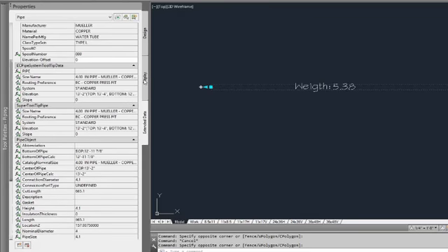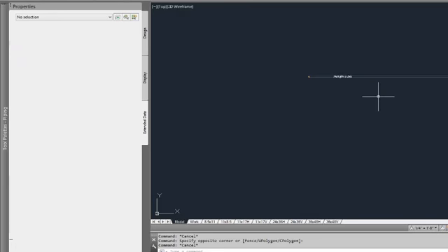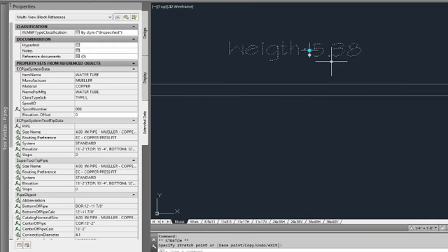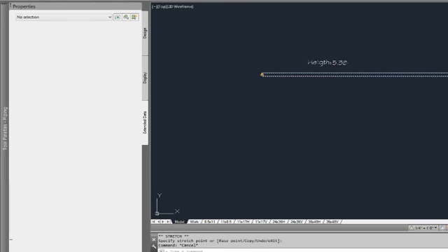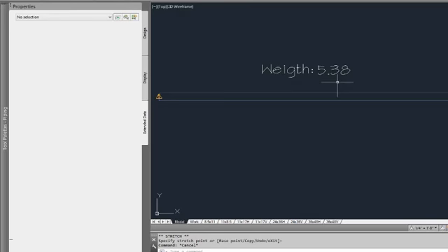So different styles of objects, pipe, pipe elbow, pipe T, pipe coupling, all of those will have a single property set that they live in, the pipe object property set, or in our case, the pipe system data. So we got a little sidetracked there, but we learned a little bit more. We learned how to create property sets that were a mixture of text and properties, and we learned to always run pipe schedule data as much as possible.